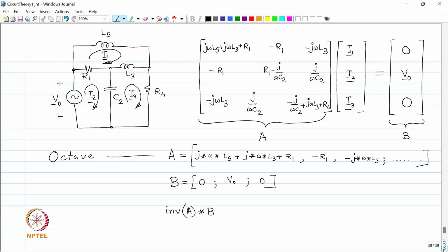Okay, great. Now, I am going to throw in some complications over here. You will be able to do it with node voltage also, the same thing, straightforward, just ground one of the nodes, define all the potentials V 1, V 2, V 3, and then carry on. You will be able to do the same thing with the node voltage method. Now, I am going to throw in some complication over here. I am going to put some dots. What does this mean?